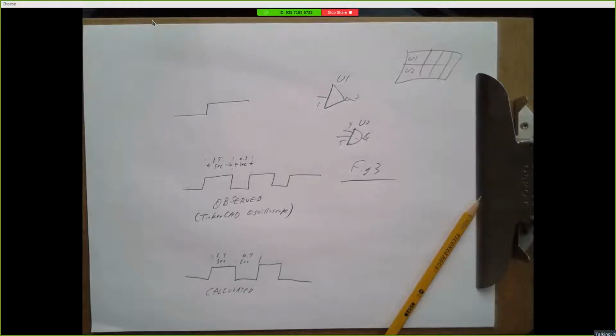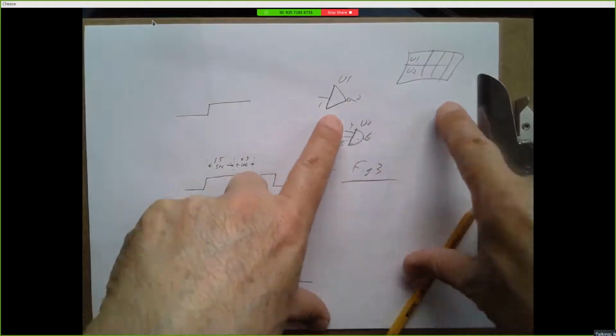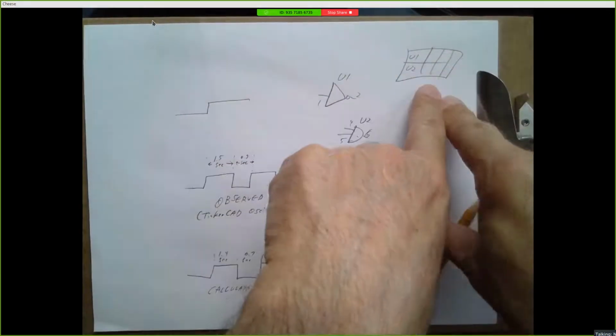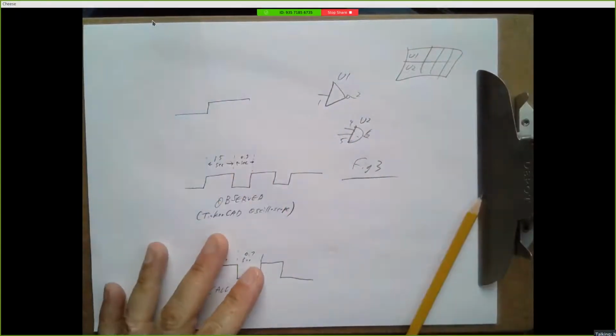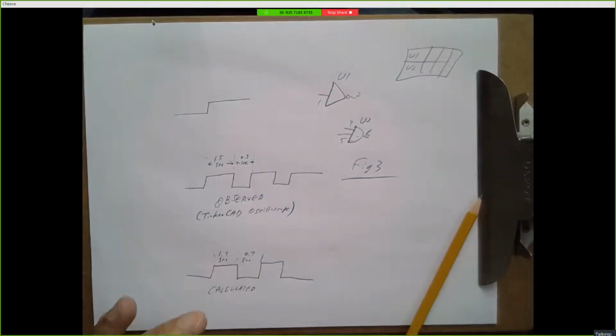That will completely explain to anybody who knows how to do digital logic and how to use Tinkercad, how to repeat what you've done up to that point. They look at this, they know they need an inverter, which is a 7404, an AND gate, which is a 7408. They hook wires between these pins, right? That's a universal language for people who are versed in digital logic. So your procedure can be, build the circuit shown in figure 5A in Tinkercad, and start the simulation, right? See what it does.